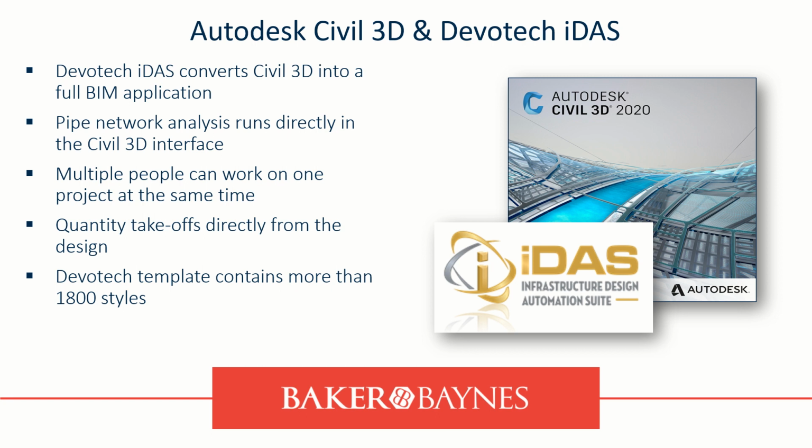Now, if you've used Civil 3D by default, you should know that once you do your pipe networks, first of all, it's not that dynamic, but I do see that the 2021 updates are really, really good, so check them out. But in terms of the analysis, you would still need to export it to storm and sanitary analysis, do your calculations or your analysis, and then bring it back into Civil 3D. And there's a lot of confusion or loss of interest between that step, especially amongst users, because the interface is completely different to Civil 3D.